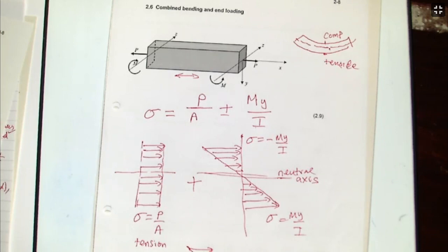If you bend that upwards, right at the top, that will be in compression. At the base here will be in tension. If I continue to bend so far, then this will just break here because that tensile force is very high. So as you go from the base to the top, you're going to be tensile, less tensile, less tensile, become zero, and then compression, and more, and more.